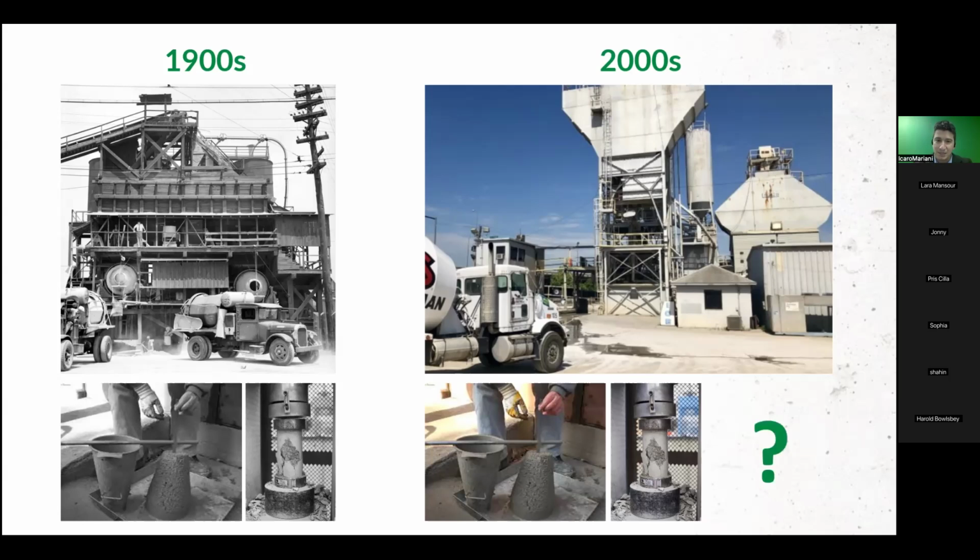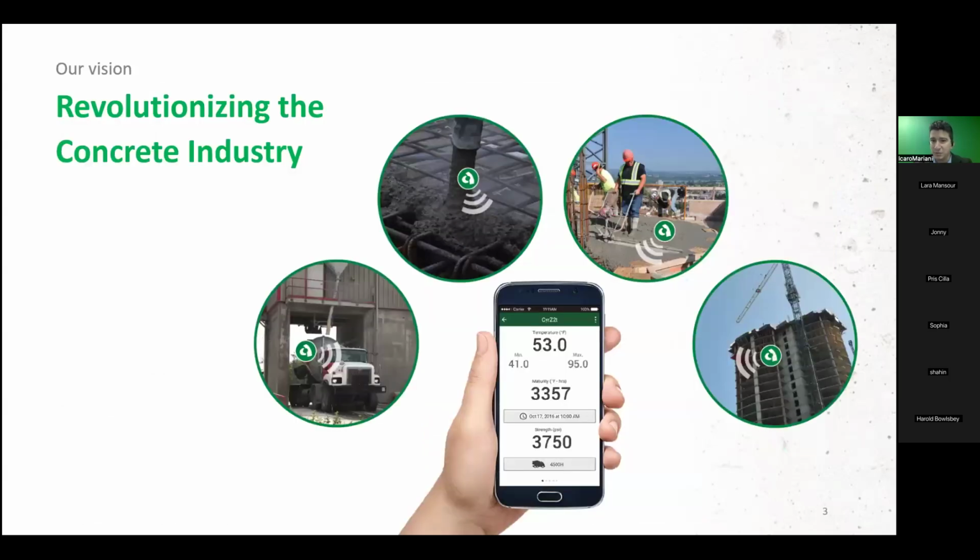And that leads me to the second slide, which is: what is the goal of introducing IoT and AI in the construction industry? So we can actually integrate everything from batching the concrete at the batch plant, putting it at the job site, monitoring it after the placement, and actually having the go-ahead to perform critical operations when the time comes, such as stressing cables in post-tension decks or removing forms on high-rise buildings. Does that make sense? Yeah, it does.